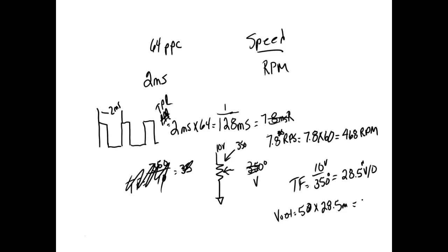So then we would know our transfer function, and we can scale that 1024 over to what it's supposed to be, right? That makes sense? So if it comes in and gives me 5.6 volts on the output, it would give me 15.73 degrees. That's what the scaler would do. It would actually tell me what that means, like temperature and stuff like that.